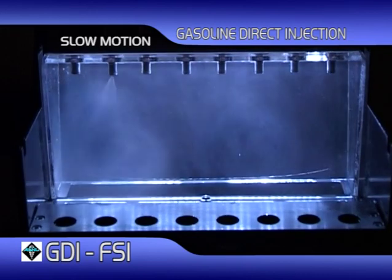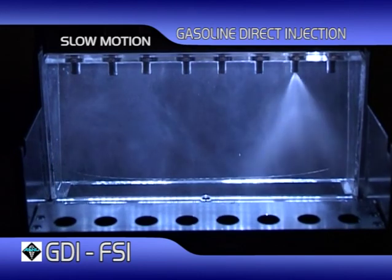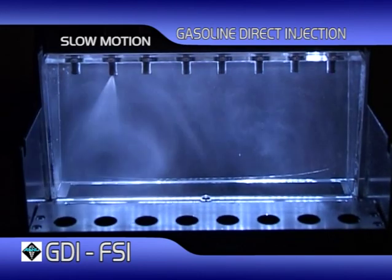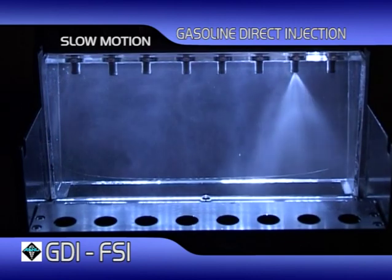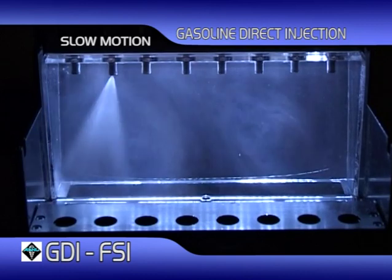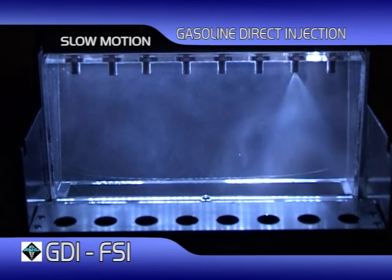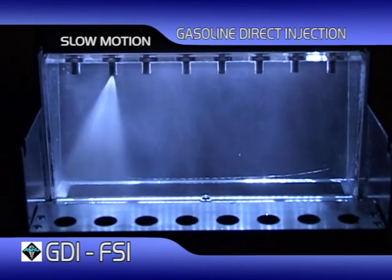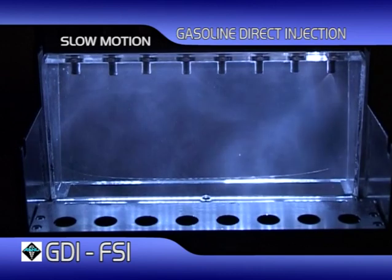Any permanent change in the fuel distribution or atomization are corrected by the long-term fuel trim. This fuel trim adjustment is not correcting the problem, it's adjusting the engine to compensate for it. All engines with direct injection have adaptive engine management systems. These systems are actually masking a deterioration in the injector's performance.